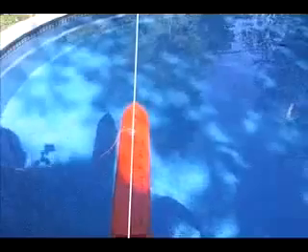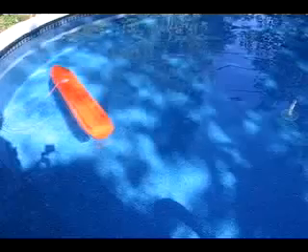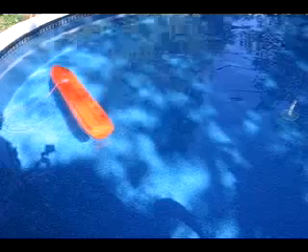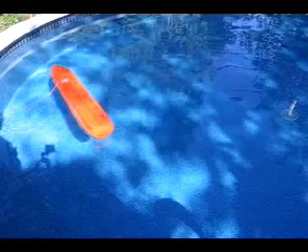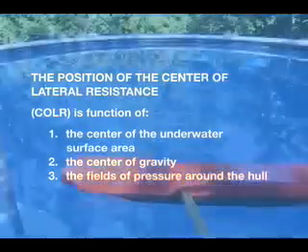A force acting ahead of the center of lateral resistance will rotate the ship in a different direction than the same force acting astern of the center of lateral resistance. The lateral resistance can also be called hydraulic lift. The position of the center of lateral resistance is function of the center of the underwater surface area, the center of gravity, and the fields of pressure around the hull.